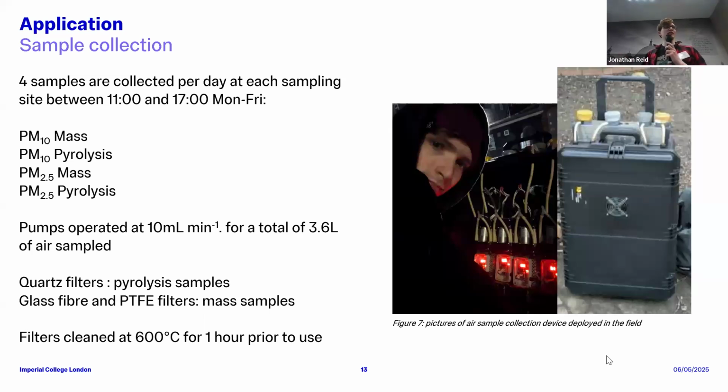And I sampled for 6 hours a day. The reason I sampled for 6 hours a day is because that is about how long you can maintain the flow rate of 10 litres per minute off those batteries before they need recharging. It's one of the limitations of trying to sample in remote locations.